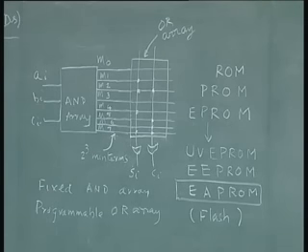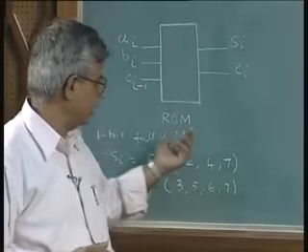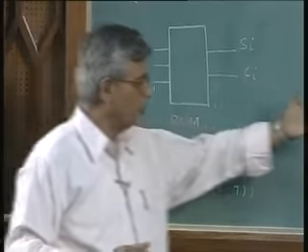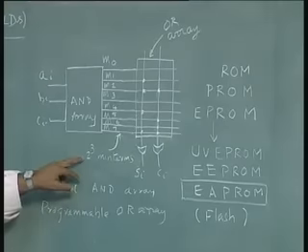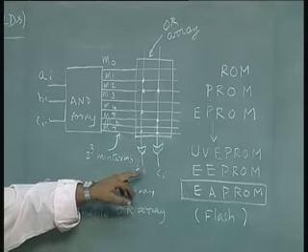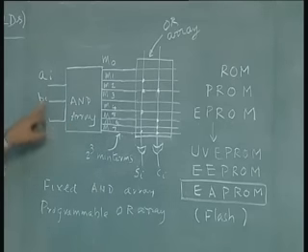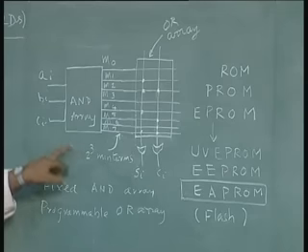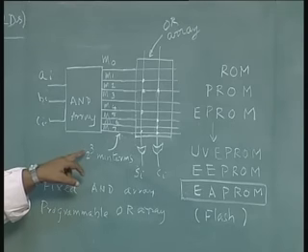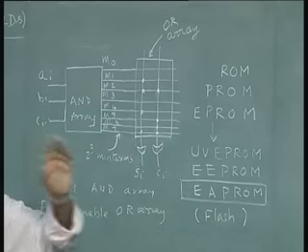ROM is used in a large number of applications. The size of the ROM required is proportional to the number of inputs and number of outputs. Number of inputs increases the number of min terms and number of outputs increases the number of OR terms. The AND term explosion is exponential. If I had one more input, instead of 3 inputs, if I had 4 inputs, I will have 2 power 4, which is 16 min terms. So, every one extra input I need a 2 power addition in the number of min terms. On the other hand, OR terms will increase only by the number of outputs.